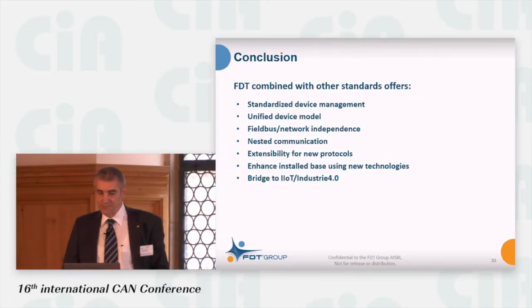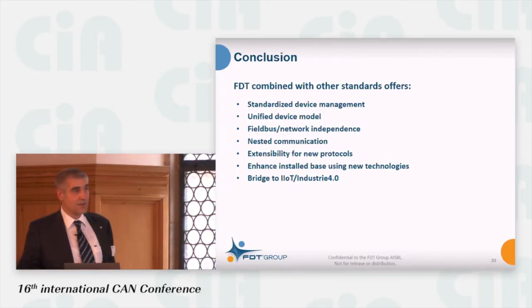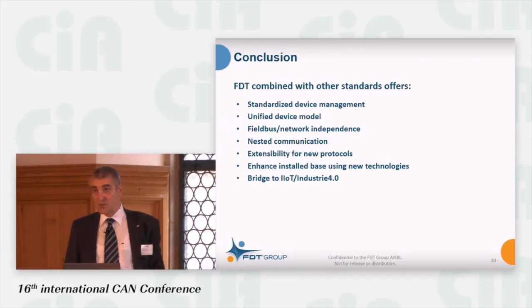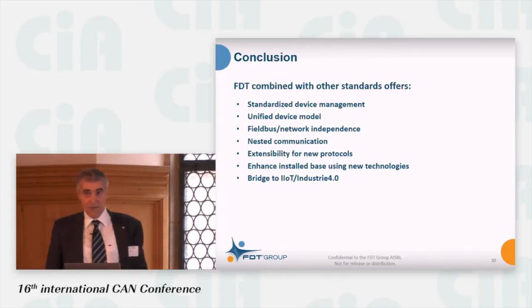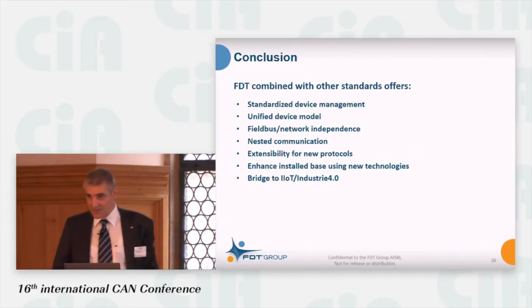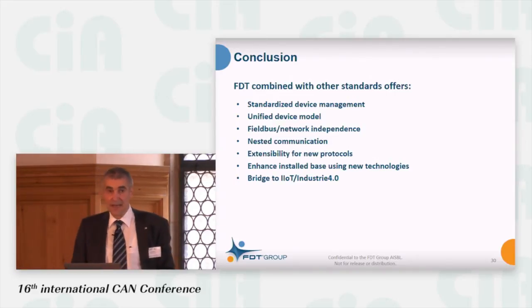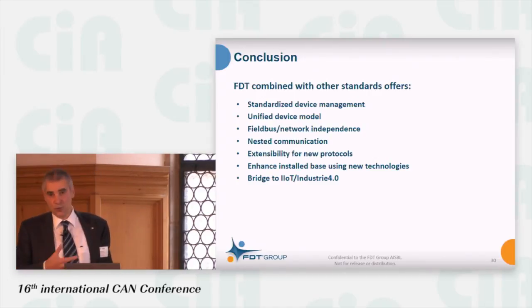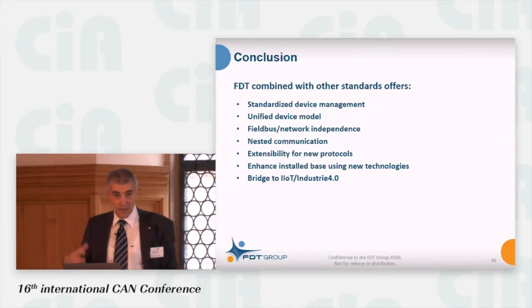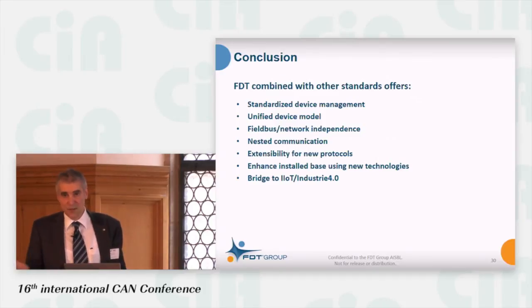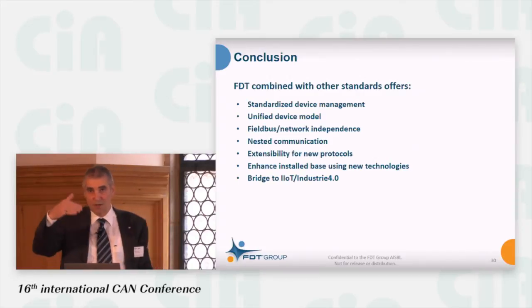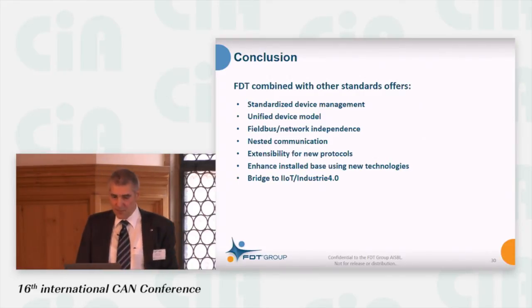So my conclusion: FDT is really able to be combined with other standards, which is very helpful. So we do not invest in and invent everything new. We use what is there for future steps. And what we provide is a standardized device management in the field. We now have a unified device model we can provide to other systems. We are network and field bus independent, so no matter what field bus it is, we can integrate it. We have this nested communication so that we are crossing more than one level in the network.